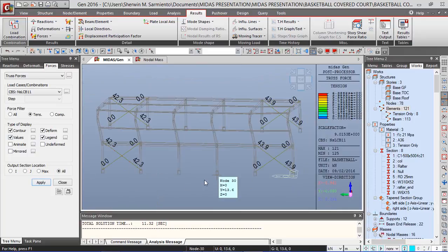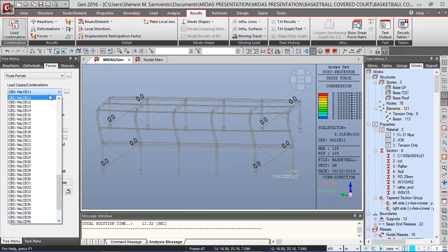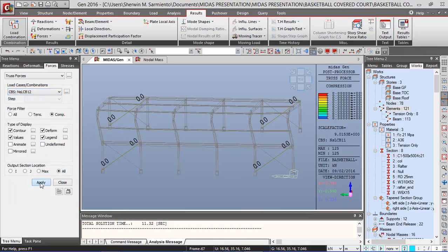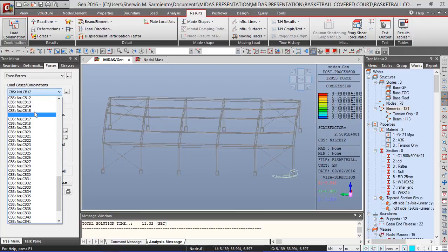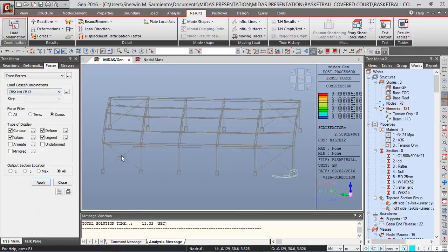As you can see, these are the forces on the load combination where the earthquake is going along X, or along Y, I'm sorry, along Y. And for compression, they take no compression. So pretty much you can just check this, and after that you can design for these tension only elements.